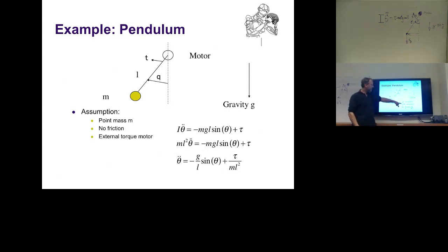Next thing, let's see whether we can simplify the inertia of a point mass. It's the reason why we made it a point mass, because it's so simple. The inertia of a point mass I is simply the mass times the distance squared relative to the rotation point. So here's a mass. It rotates about this point with distance L. So ml squared is the inertia of a point mass. Good. And so we can actually insert this here. Beauty about a whiteboard, I can erase stuff and just write ml squared here.